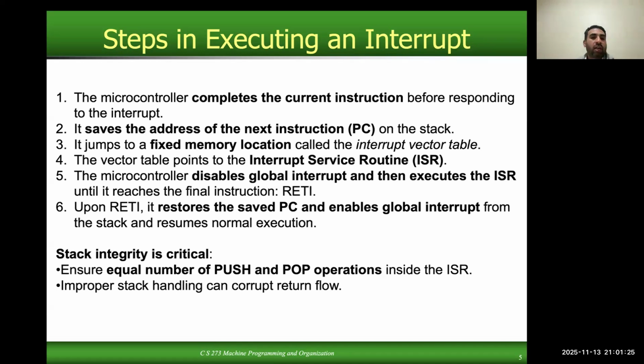If there are not equal number of push and pop instructions, your stack handling will be improper, and as a result, you will not have the correct return address.